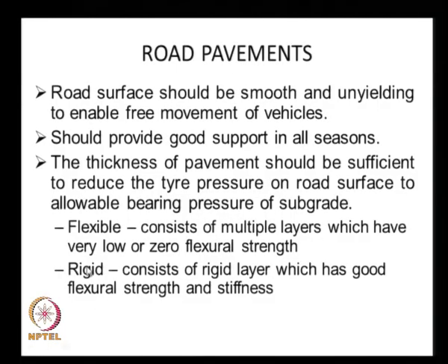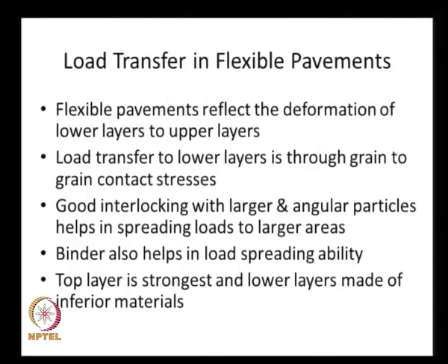And then the other type of road pavement is the rigid pavement, like a reinforced concrete pavement. This consists of a rigid layer which has excellent flexural strength and stiffness. So no matter what is below that pavement, the load is distributed over a very wide area, thus ensuring that the rider comfort is ensured.